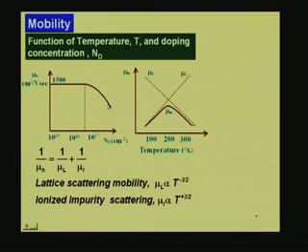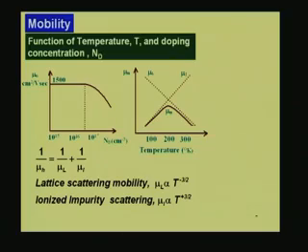And this mobility fall is due to the scattering of the carriers by those ionized impurities. Because the more dopants are there, those dopants prevent the electrons from moving smoothly. They get knocked or scattered by these impurities. That is why when the doping becomes high, scattering becomes more, the velocities fall.